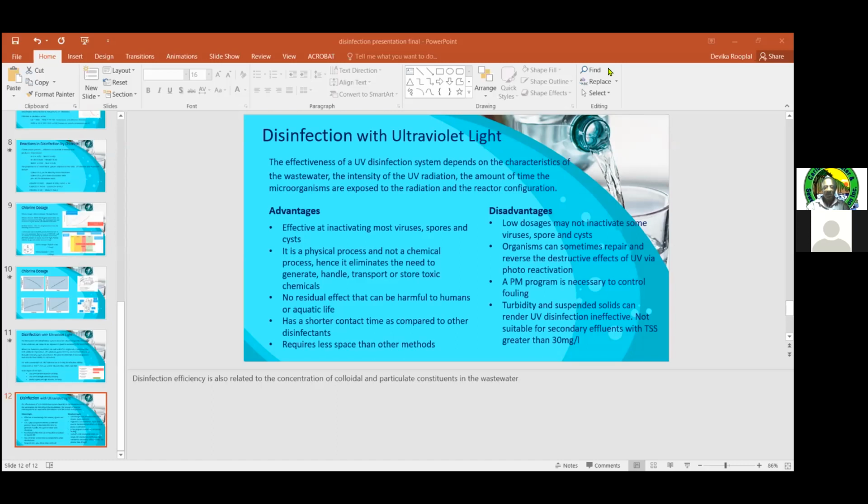Well, yes and no, but more yes, because your turbidity would be as a result of something, and if the cause of that turbidity is consuming your chlorine, it's whether that is affecting your chlorine demand. If it is increasing your chlorine demand, then you will end up dosing more chlorine because you have to overcome that chlorine demand.